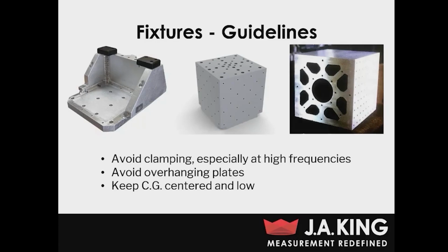You also want to make sure that you keep your center of gravity as centered over the shaker as possible and as low as possible. And this is going to help avoid causing any moment on the actual shaker itself.